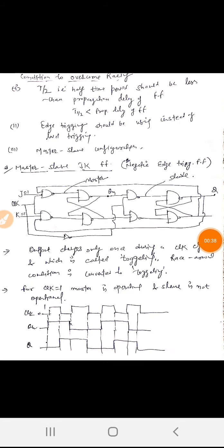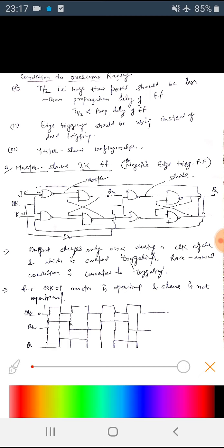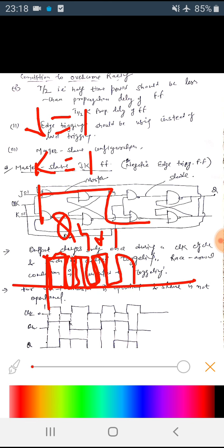In last lecture we learned about the JK flip-flops, and we have also seen that when both the inputs are 1 1 in JK, when J is equal to 1 and K is equal to 1, we were getting a racing condition, that is the output Q n plus 1 or the next state was toggling from 1 to 0, 0 to 1, racing in the same clock pulse.